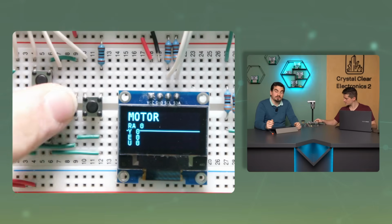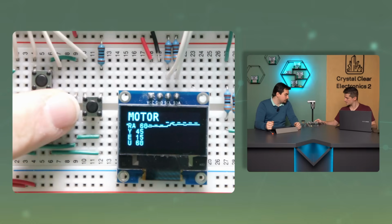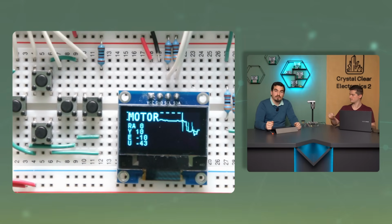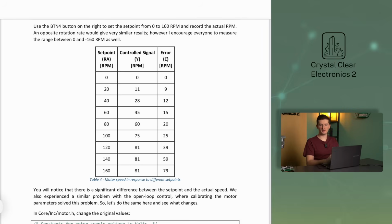Use the button on the right to set the set point from 0 to 160 RPM and record the actual RPM. An opposite rotation rate would give very similar results. You will notice that there is a significant difference between the set point and the actual speed. We also experienced a similar problem with the open loop control, where calibrating the motor parameters solved this problem.